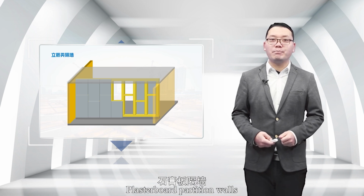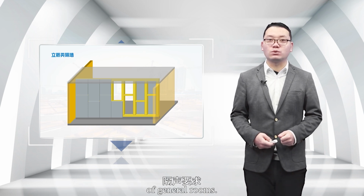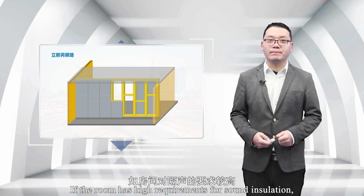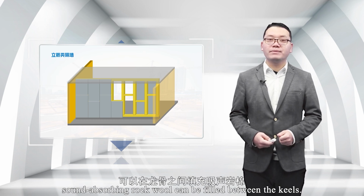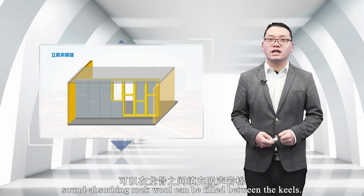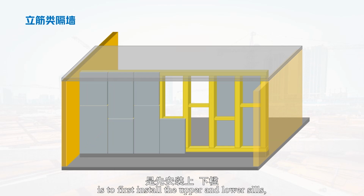Plasterboard partition walls can basically meet the sound insulation requirements of general rooms. If the room has high requirements for sound insulation, sound-absorbing rock wool can be filled between the keels. The installation process of reinforced partition walls is to first install the upper and lower sills, then install the longitudinal bars, and finally install the panels.